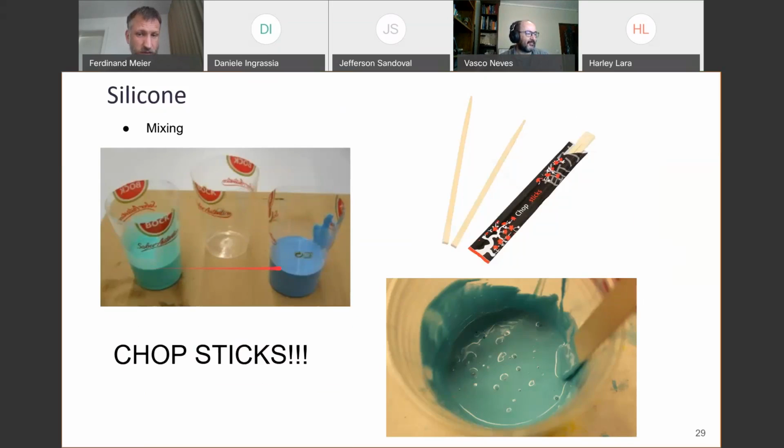I'm using 3 cups so I can pour those 2 into the third one, so I have the 2 layers side by side. Because if you put them one on top of each other, then this whole technique that Neil explained with the shearing won't work anymore. You have to somehow scoop it in order to mix the 2 liquids, but then you will get air bubbles in, and then you're doomed again.